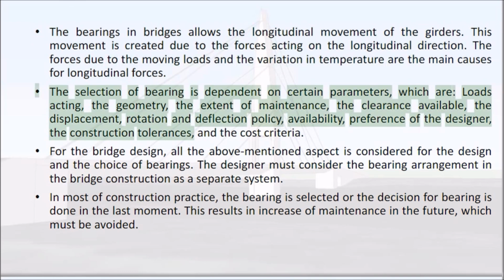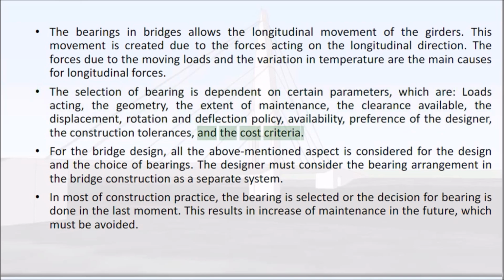The selection of bearing is dependent on certain parameters, which are the loads acting, the geometry, the extent of maintenance, the clearance available, the displacement, rotation and deflection policy, availability, preference of the designer, the construction tolerances, and the cost criteria.